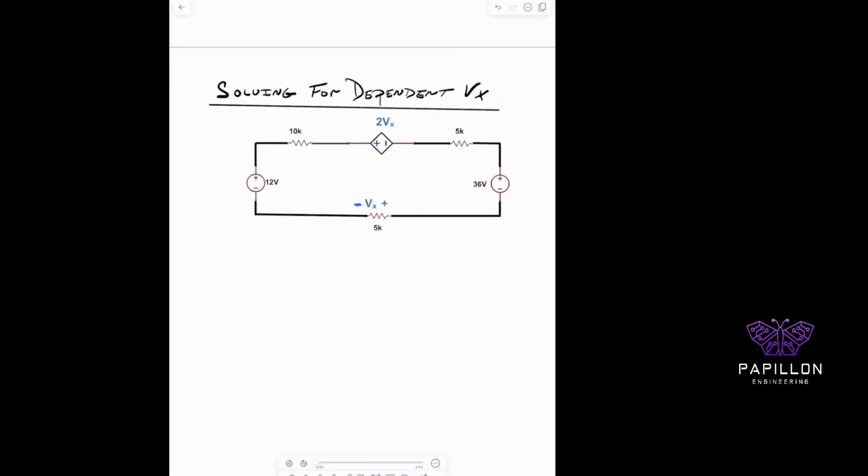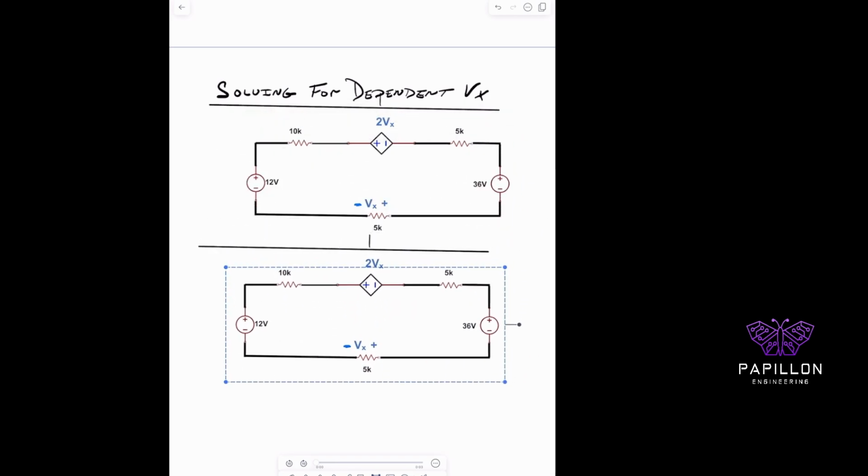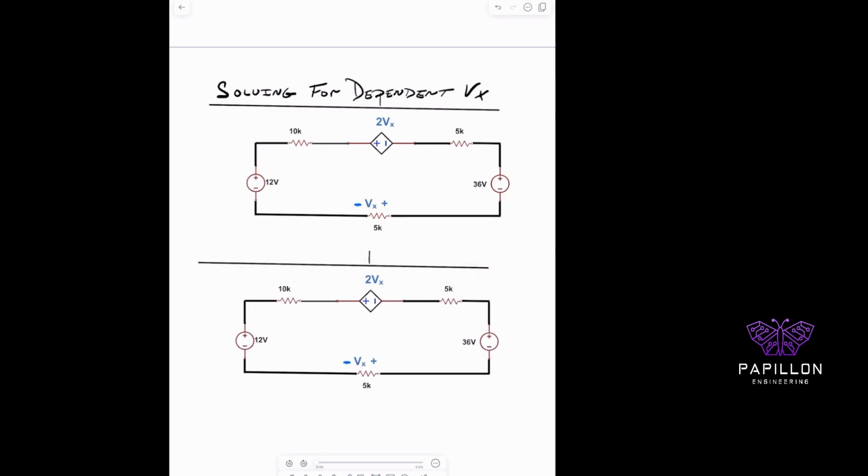So moving along to actually show you how to solve this problem by hand, because again, the simulation is great, but it's always important to enhance that experience by including hand solving. This is how you build the confidence and get way better at this. When you have a series single loop, I generally go clockwise 98-99% of the time, and I take clockwise to be positive. I'm going to call the current I something, but I source or Ix makes the most sense.